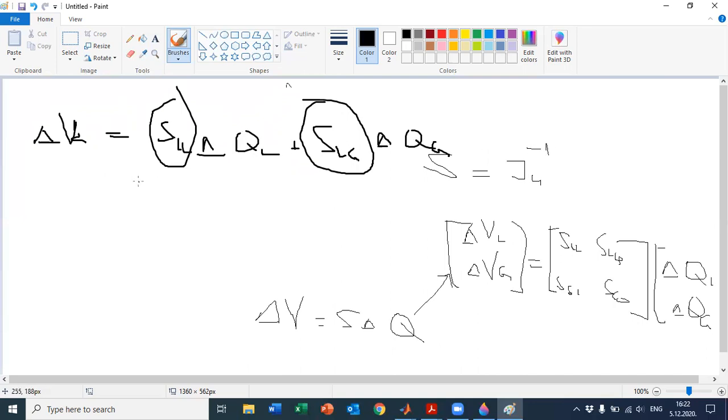In the secondary voltage control, the system operator and the voltage regulators in the system have access to the voltages of the pilot points. The goal of the secondary voltage regulation is that the deviation of the voltages in the pilot nodes is equal to zero.